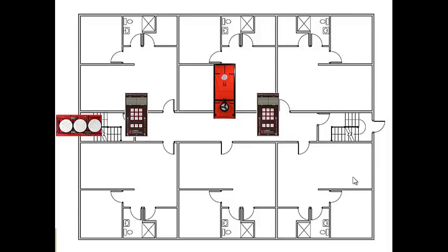Now, we talked about that fully guarded test where we're controlling multiple fans, or maybe it's just one fan, to get the whole building at a common pressure, and then we're testing unit by unit individually to get leakage to the outside for each unit. So how would we set up the tubing connections for this?